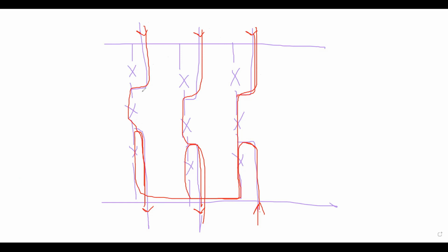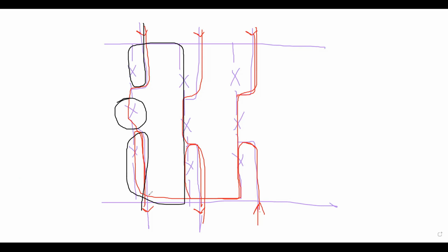It flows. So suppose if one of the breakers fails, suppose this middle breaker fails, then this power will take this route and it will come like this and it will go like this. If this breaker fails, this is the route. So every feeder should be rated for the maximum capacity, all the load. That is why it is a very, very expensive scheme, the 1.5 breaker scheme.